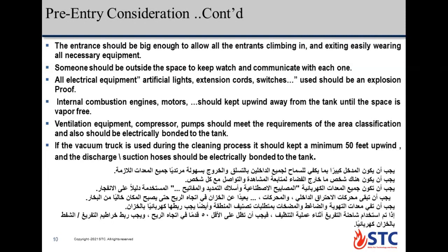If a vacuum truck is used during the cleaning process, it should be kept a minimum of 50 feet upwind, and the discharge and suction hoses should be electrically bonded to the tank. Okay.